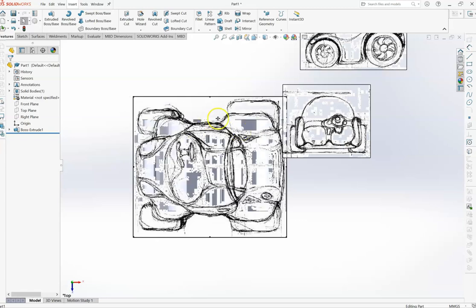Remember, they all match. All of our shapes match. So now that I've got it the right length front to back, I can now trace around the outside of this car shape, not the wheels, just the car, and chop that this direction. And that means I will end up with two faces that match my original drawings, and finally I'll do the third face. So I'm just going to pause the talking for the time being and speed up some footage so that you can see that.